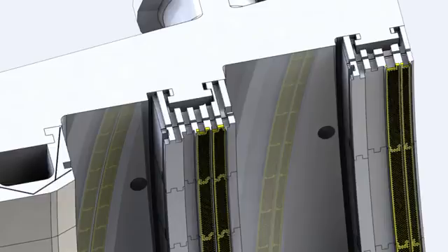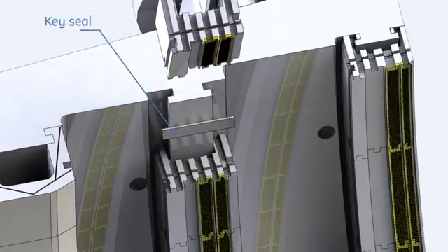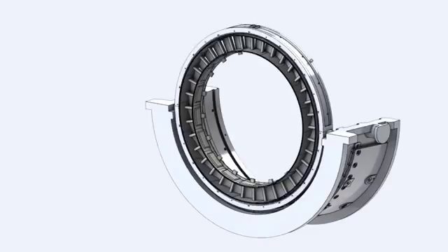The cutter teeth on the tip of the second and the third stage buckets open a slot on the honeycomb seal without any material transferred, providing tighter clearances to improve the unit efficiency. Shrouds of the last two stages are sealed by interconnecting tongues and grooves and by key seals. In the first stage nozzles, hot gases received from the combustion system are expanded and directed to the first stage